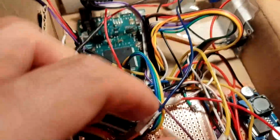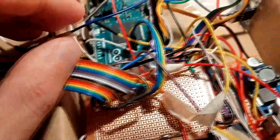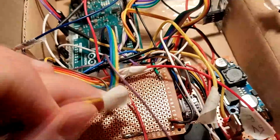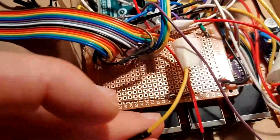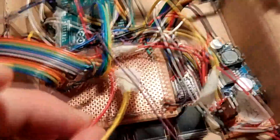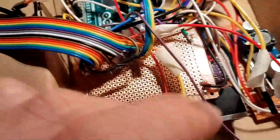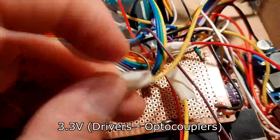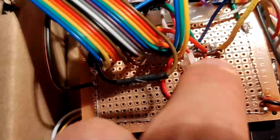Now we are about to solder all the 3.3 volt cables. Here I have the switch. There is another one here for the screen. You can see the wiring diagram so as not to forget any of them. This one is for the rotary encoder. There is another one below, coming from the optocouplers for the autoguiding. So I made a big drop of solder and soldered all the wires together.